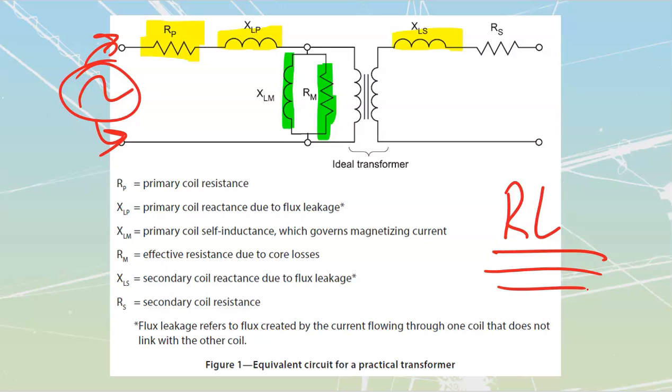All right, let's talk about the energy losses. Is there energy lost in a transformer? Absolutely there is. As soon as we feel heat, right? We've got heat that is going to come off of this thing. We know that that is going to be energy that is not being transferred out to wherever my load is going to be, right? So we do have to measure those losses.